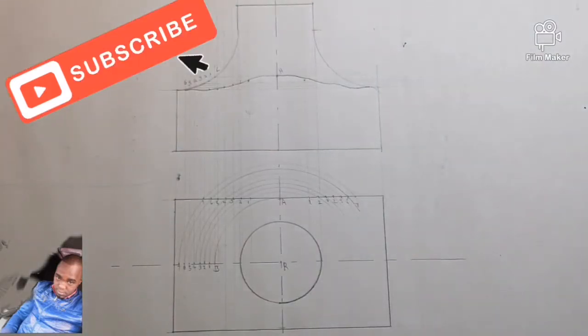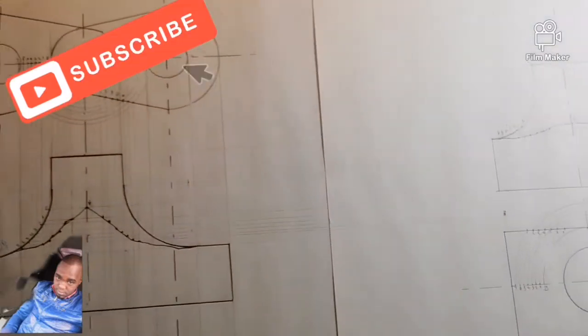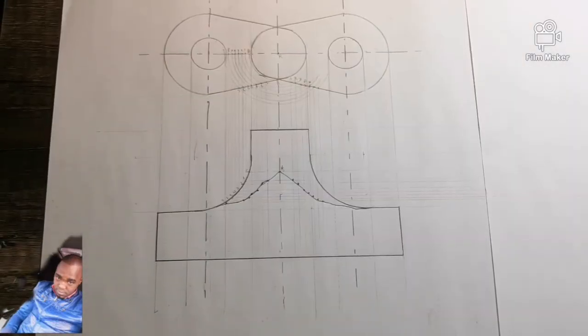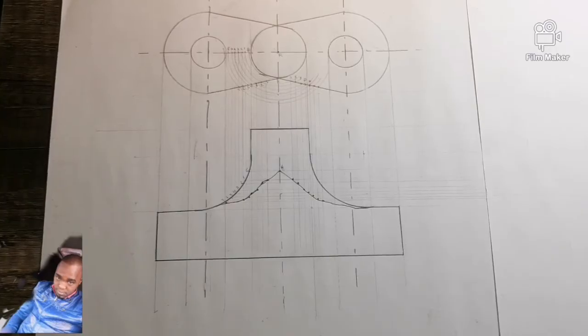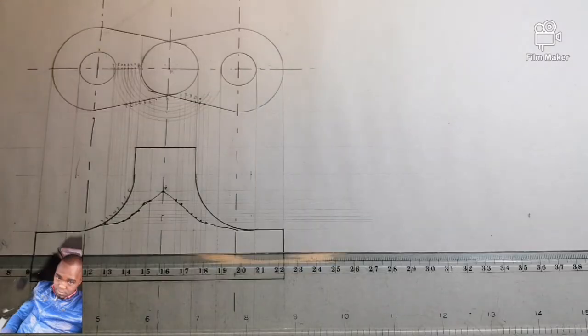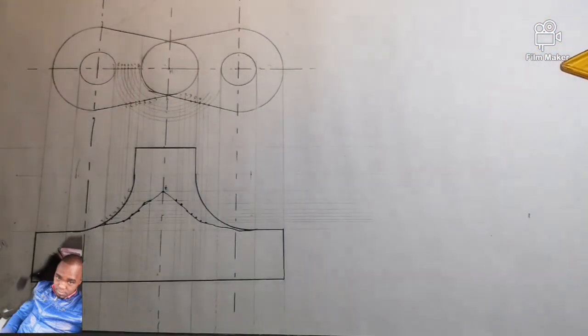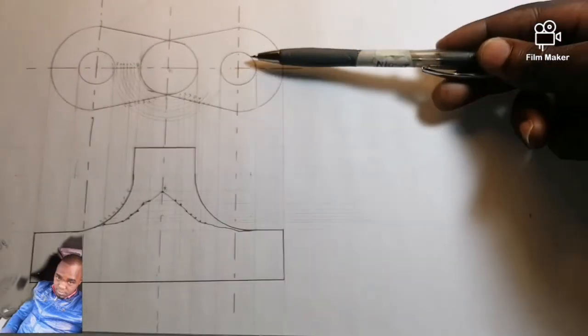You understand? So we don't just draw. We follow the protocol. We follow the method. So your line of penetration is going to be something of this nature. So let's say the question asks you to project the left view. The left view, remember this was given inward in third angle orthographic projection. So this is not going to be your left, it's going to be what? Your right, because this is front, this is top.